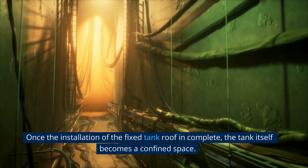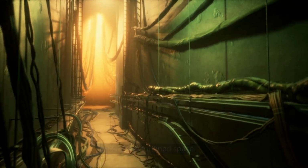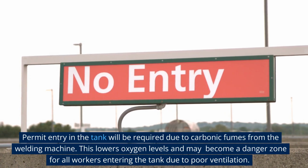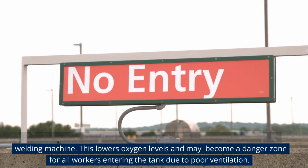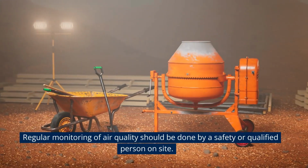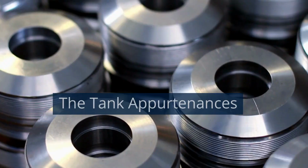Once the installation of the fixed tank roof is complete, the tank itself becomes a confined space. Permit entry in the tank will be required due to carbon fumes from the welding machine. This lowers oxygen levels and may become a danger zone for all workers entering the tank due to poor ventilation. Regular monitoring of air quality should be done by a safety or qualified person on site.